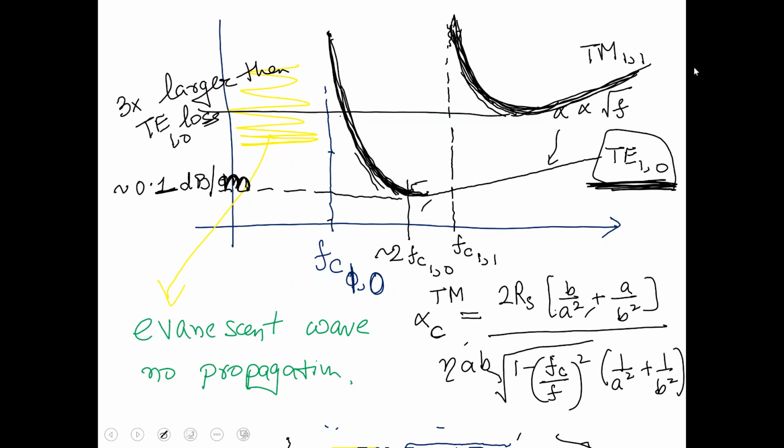If you go to optics, which is now 500 terahertz, or anywhere, like if you're doing optical communication, that's 193 terahertz, the metal is very lossy there. And you have seen that yourselves. If you try to pass light through metal, there's hardly any light going through, right? So you know that metals have heavy loss in optics. Even these rectangular waveguides completely fail there. Nobody even tries to do any rectangular waveguides in the optics domain. You go with dielectric waveguides over there.